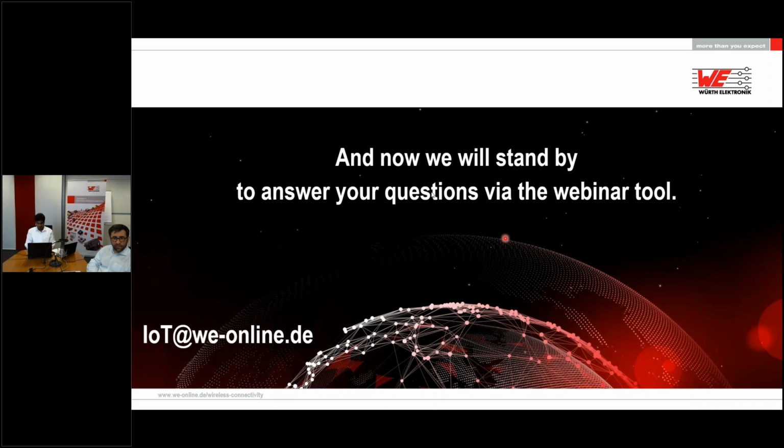Maybe one first question. You mentioned scalability, flexibility, and security of the system. Can you please elaborate on the security aspects? Yes, for sure. Security with respect to IoT has to be considered from end to end, from the sensor to the cloud. At the lower levels, you have to consider that your device has to be really secure, which means secure boot. Secure boot basically means only the firmware which is verified by the manufacturer should be allowed to run on the microcontroller.